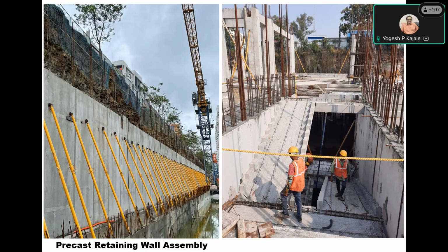As far as horizontal joints are concerned, in cast in situ construction, we get a completely in situ stitching over the lower story element. In precast, again, that horizontal joint is critical. So precast versus cast in situ, the major difference is in the jointing method.